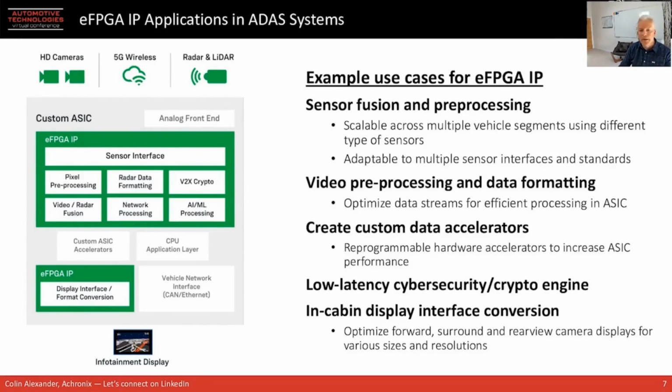So here is a block diagram showing the different applications that can be accelerated in embedded FPGA IP in an automotive environment. The eFPGA can be used to offload other CPU, analog front-end, and dedicated ASIC accelerators. It can be designed to support shared memory and coherency schemes for efficient use of SoC resources. Specifically, one or more eFPGA tiles can be used on a SoC to support efficient, low-latency workload acceleration of multiple tasks. Each eFPGA tile could support various workload accelerators.